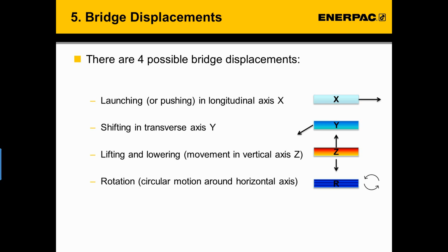Another important element to look for when studying the bridge construction file is the displacement of the different building blocks of the bridge. These different movements call for different controlled hydraulic solutions. We look at launching or pushing, shifting, lifting and lowering, and rotation.